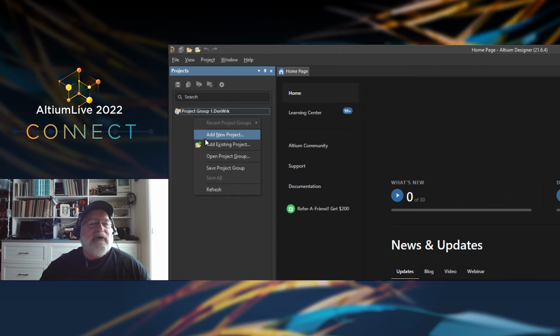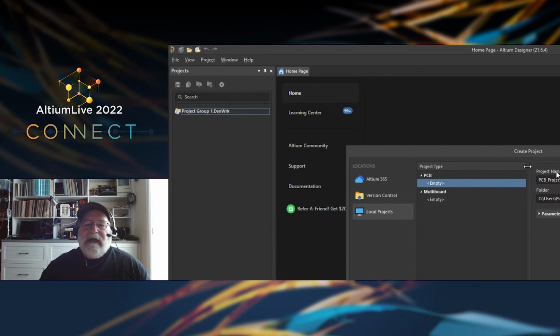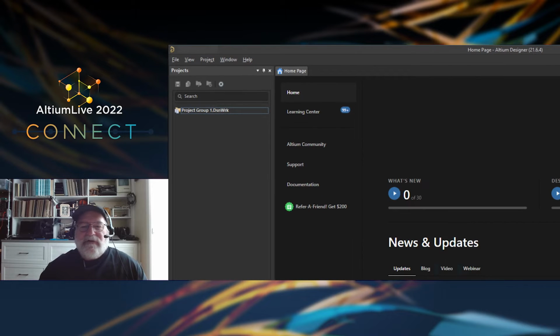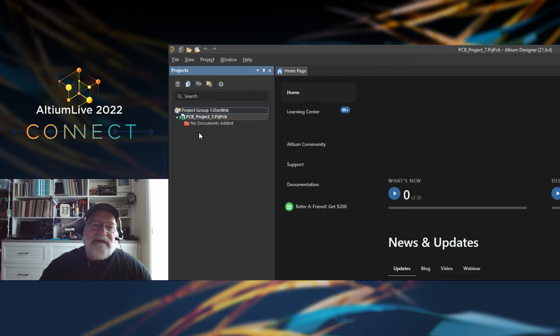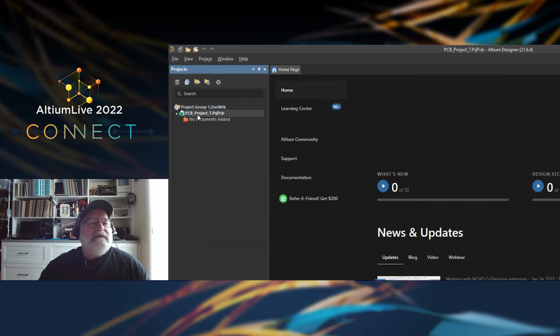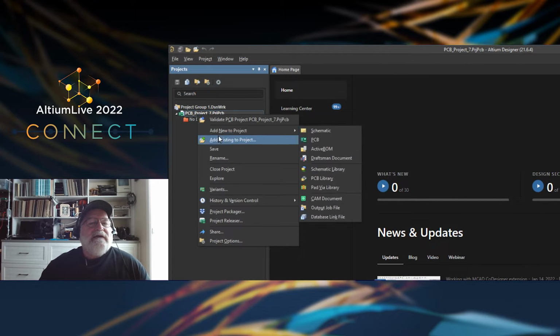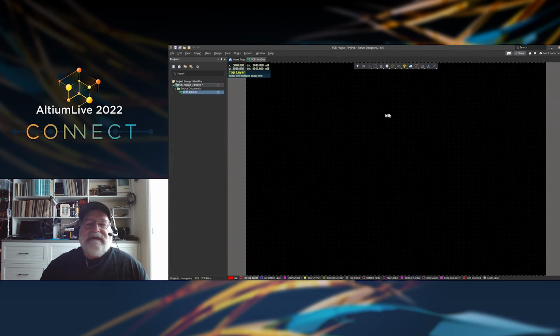I'm going to create a new project, so add new project, and I'm going to just use absolute basic default, nothing fancy. And now, in order to access the built-in 2D field solver, we need a PCB page. And to do that, I'm going to add new to project. Let's see, I want a PCB. And so here's my PCB.